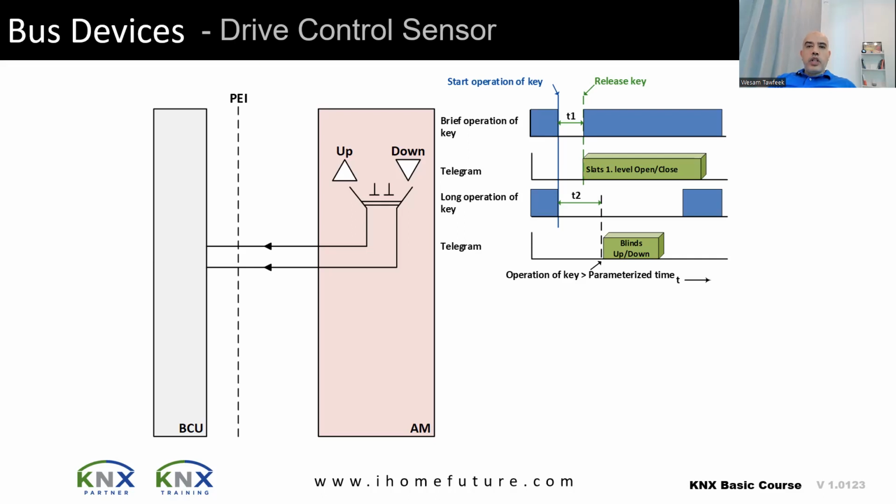Okay? So in your configuration, you can configure the time in the parameters, in the KNX, to tell it how long it should keep giving power. So I kept pressing here. So the KNX is sending to the system to move the motor up. For how long should it keep the motor up? Normally, there is a time that you get from the file of the motor itself telling you the entire duration from down to up, let's say 10 seconds or 5 seconds.